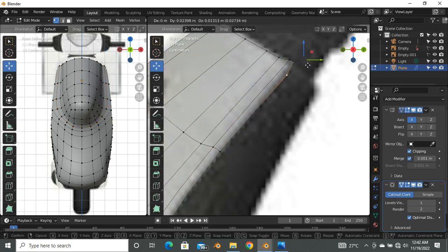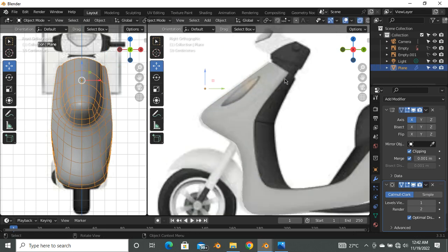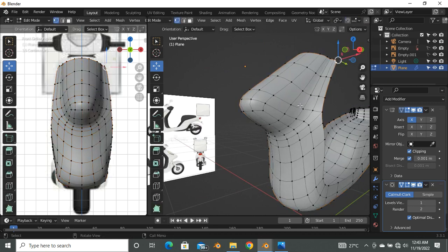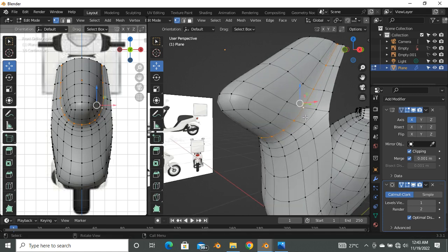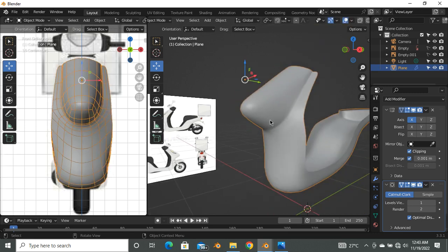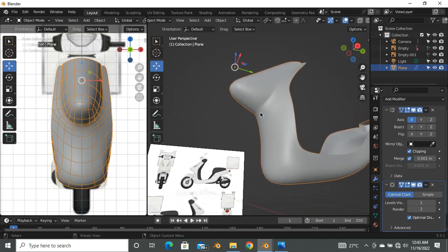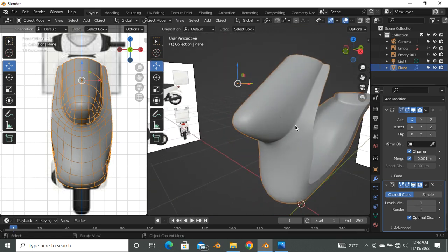Select this guy and just make some few adjustments. Tab, Control arrow, and just adding some, tab again. And select this, hold Alt, and say Control B to bevel that edge. But still, I can also do Control arrow just to add that to that point and say tab. So I have something looking like this. So this just gives us this kind of sharp edges on our bike.